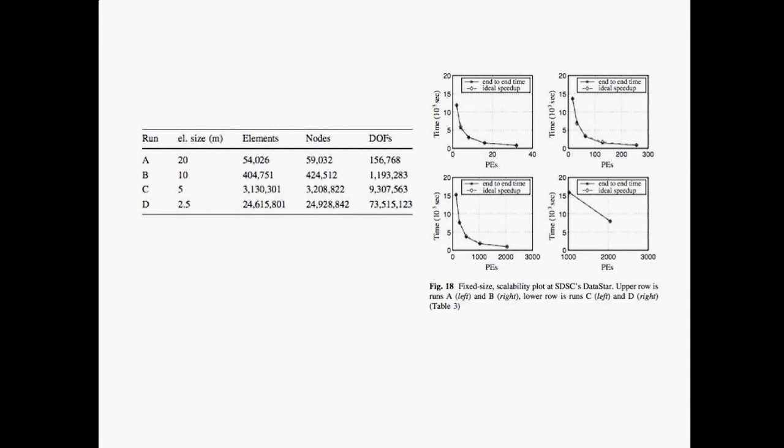And for the central difference method, he's able then to use a direct solver. So basically, the matrix is a diagonal matrix. So that scales beautifully. There's no communication required. And as I say, he's able to achieve perfect speedup just by changing his solver and changing the integration scheme. So it's something we're going to have to start looking at.